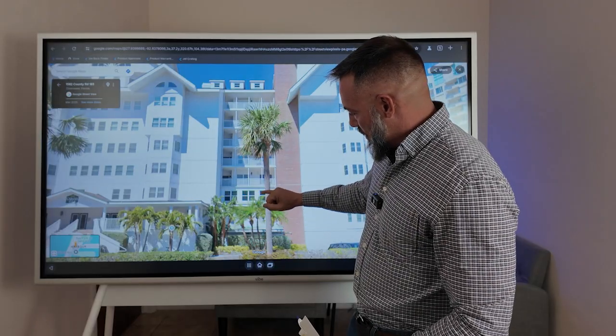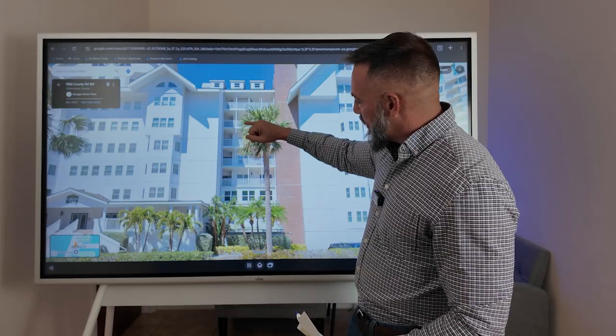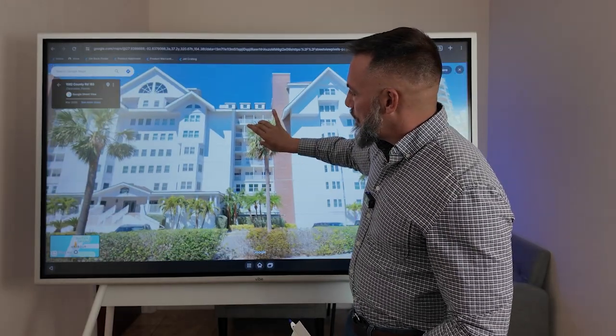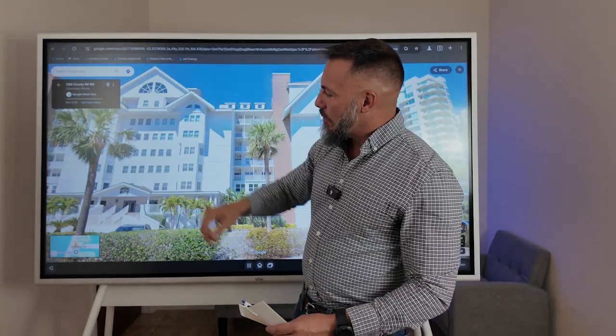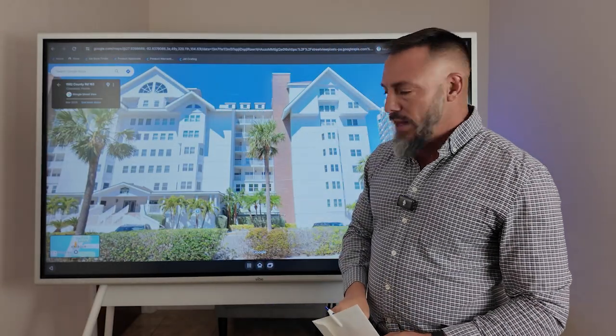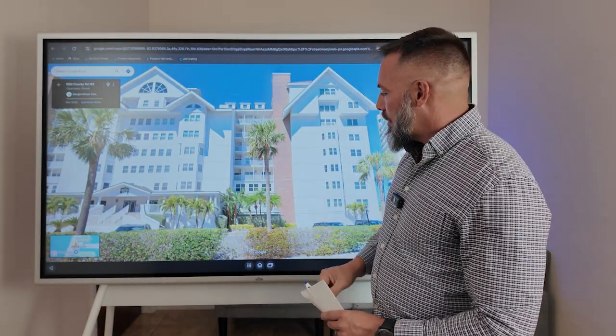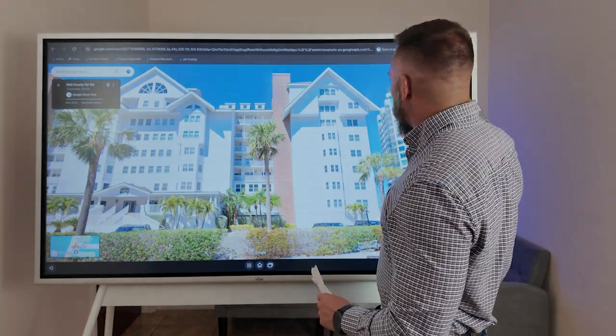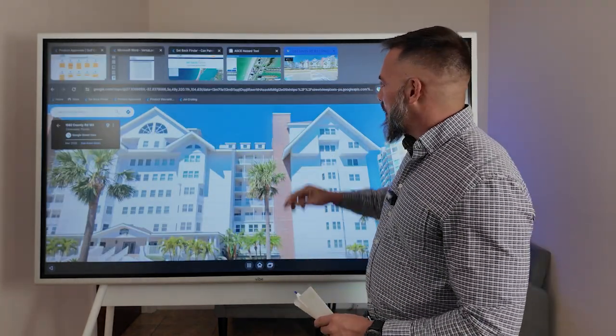10, 20, 30, 40, 50, 60, 70, 80, 90, and then the peaks up top, I think it's 104 feet. We measured it, it's 104 feet to that top peak there. So roof height is really tall. I'm right on the beach, I'm exposure D. This is worst case scenario. I know my pressure is gonna be really high.